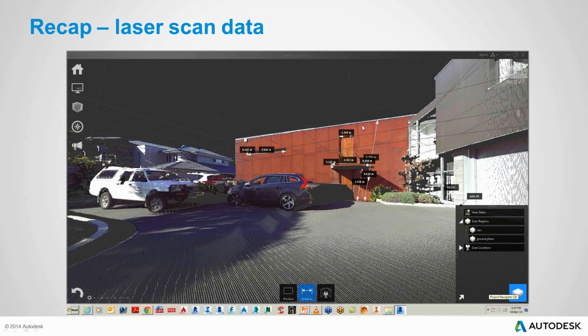You can see here I've got my Corten cladding as my kickoff point. What I can do with this laser scan is measure all the detailed information on all that survey data. I don't know if you've done your own measured surveys and you've had to go back and remeasure stuff and check on site. The great thing about point cloud data is you're going to have this perfectly accurate survey which you can open up in Recap and measure the information and check it. You can bring in numerous scans and then stitch them together. In this case we've got maybe half a dozen scans. We've stitched them together in Recap. But perhaps if we did a few more, we could get more of Brett's car and maybe more of the neighboring properties, should we need that in our workflow.